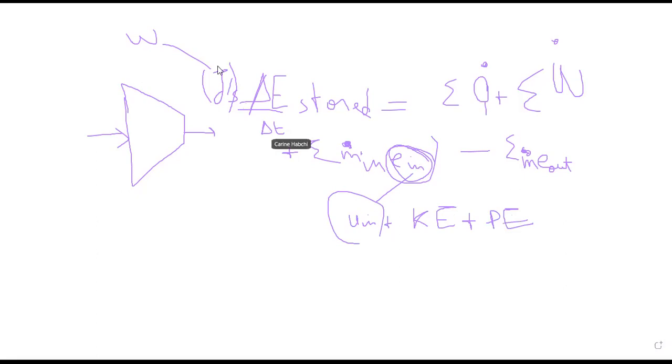And if they don't tell you this and you are able to calculate them, you can do it. And you can see that they will be negligible compared to the change in internal energy. So this is why, in general, they are very small, we neglect them. If I give you the velocity at the inlet and the outlet, no need to neglect. You can calculate it and see the amount of this energy compared to internal.